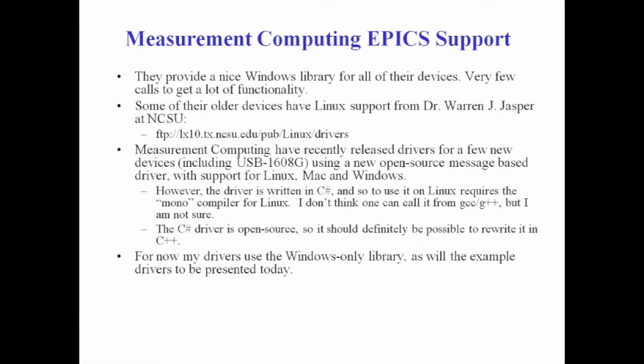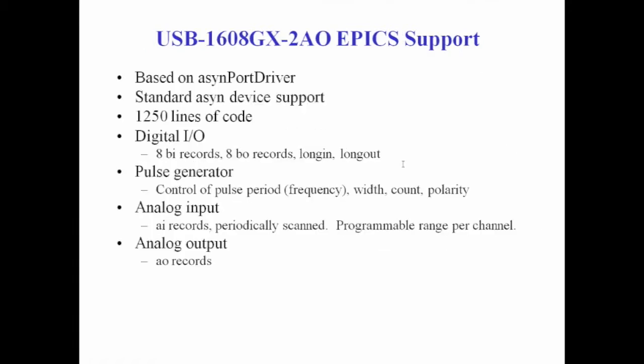So for now, my drivers all use the Windows-only library, as will the example drivers to be presented here today. This support is based on asyn port driver, uses standard asyn device support. The full-blown driver is 1,250 lines of code. It supports the digital I/O with BO and BI, long in records, a pulse generator, analog input, analog output with AO records.